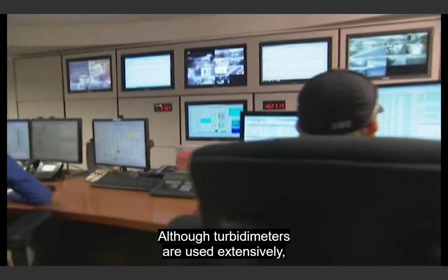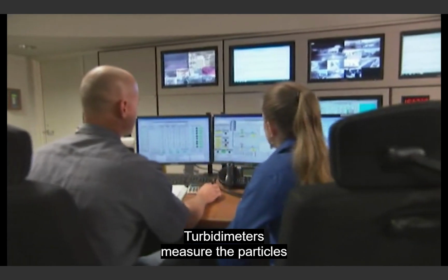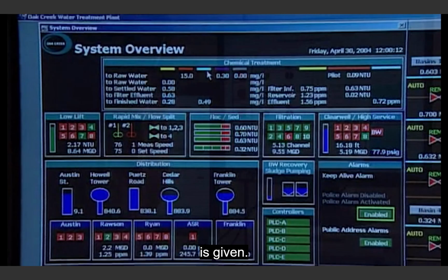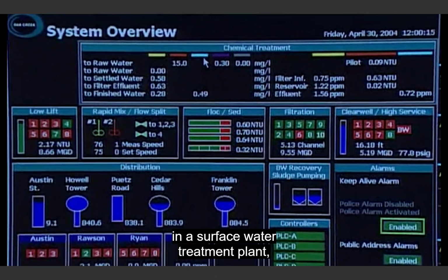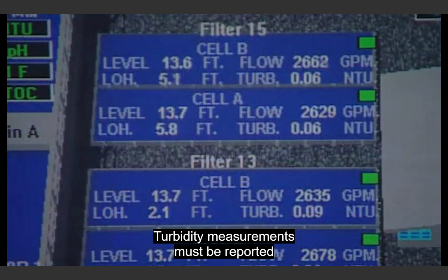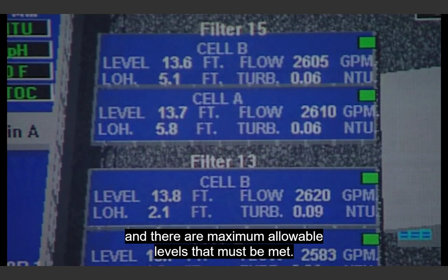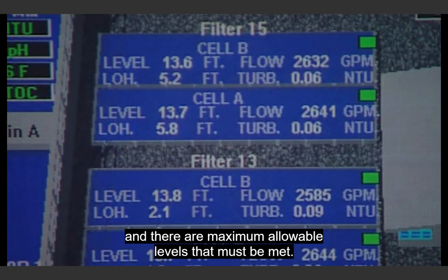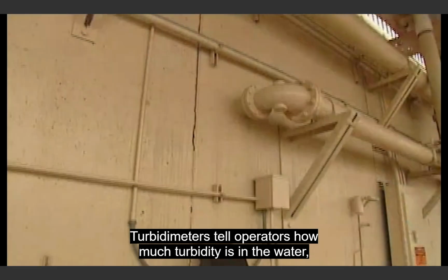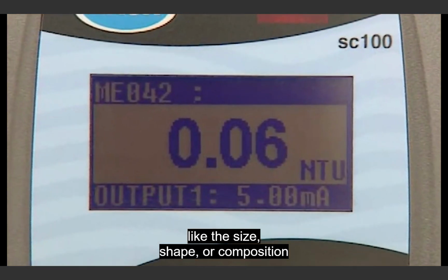Although turbidimeters are used extensively, they do have some limitations. Turbidimeters measure the particles in the sample as a whole, but little additional information is given. Turbidity is a regulated parameter in a surface water treatment plant, whereas particle counts are not. Turbidity measurements must be reported to the proper regulatory agency each month, and there are maximum allowable levels that must be met. Turbidimeters tell operators how much turbidity is in the water, but they don't provide more specific information, like the size, shape, or composition of particles in the water.